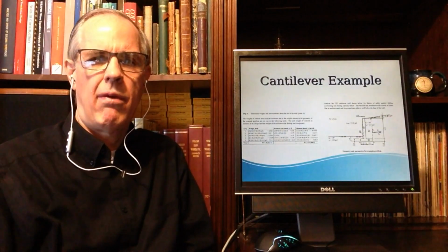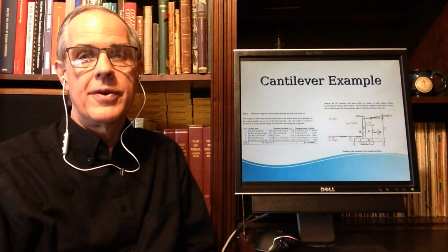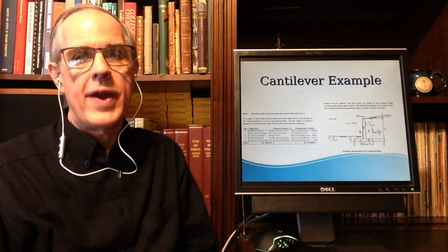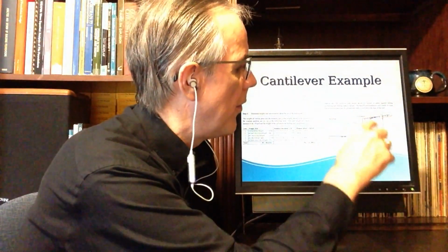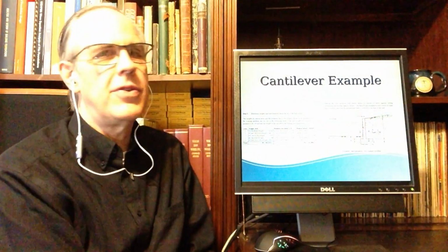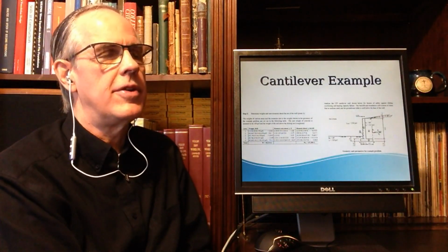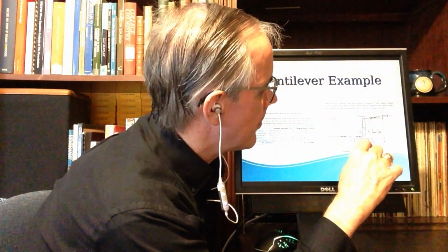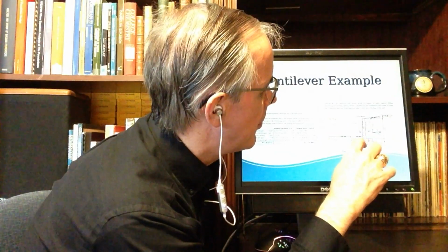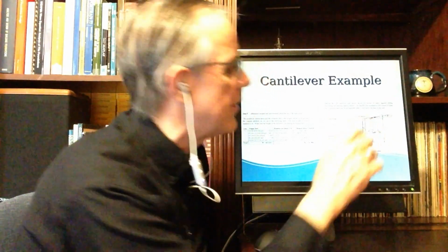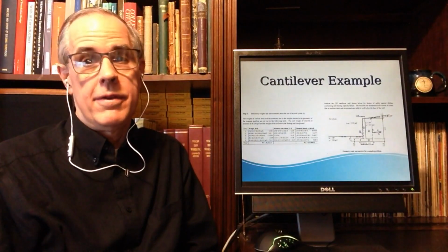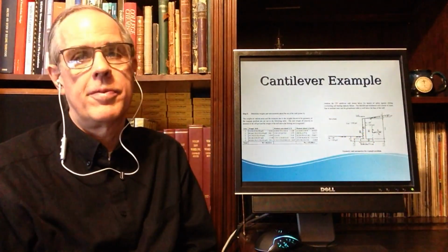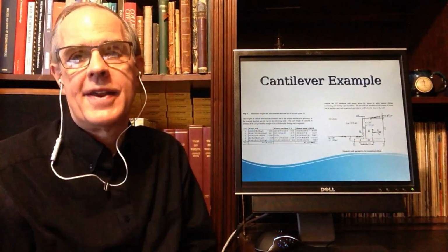What are they? What we're doing here is, there are 2 ways to compute the weight per unit wall of, say, this whole mass. We've got 2 things going against us. One of them is that the geometry is a little funky. We've got angled things here. For example, this base is 2.3 feet wide at the base, but only 1.6 at the top. Why is that? This is a cantilever wall. Cantilever moments you're going to have down here at the base, so that's for structural purposes. Therefore, we don't have a nice rectangle.